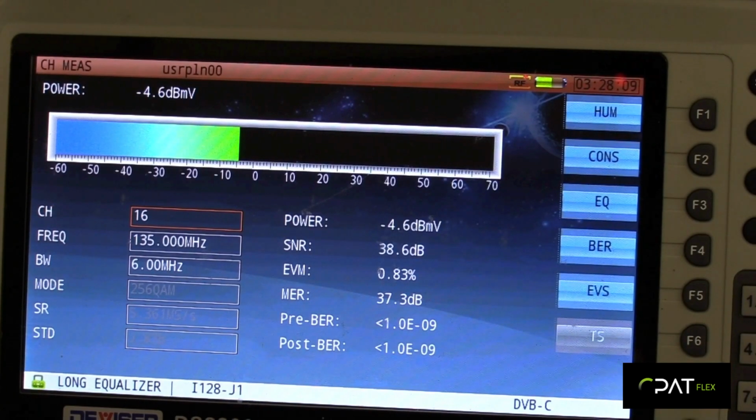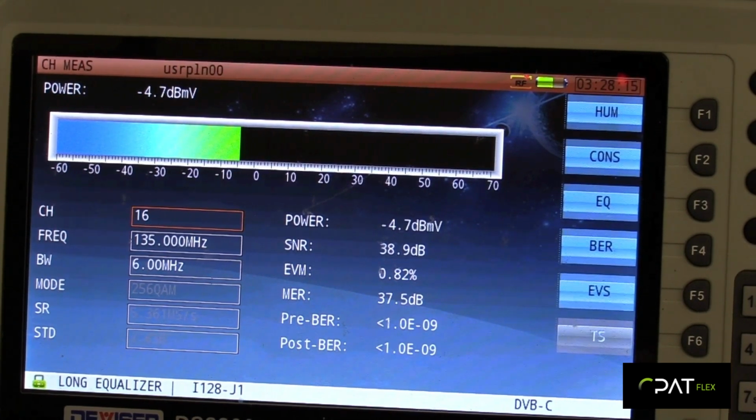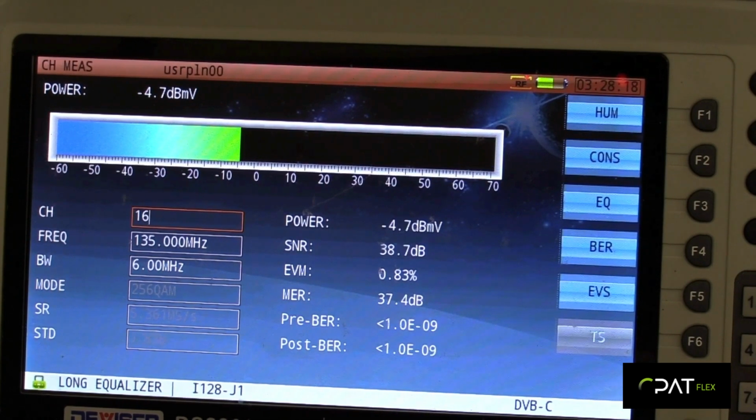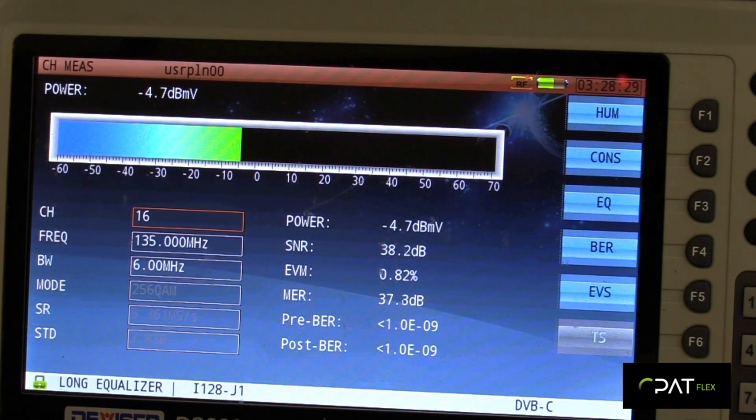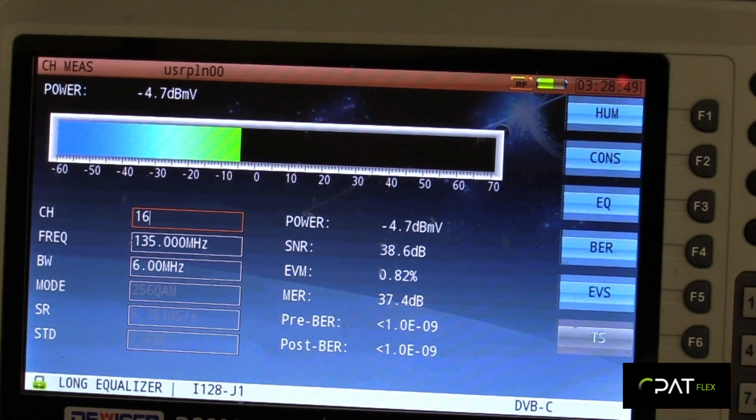Since we need to make digital and analog measurements, ideally you could use a QAM analyzer such as the AT2500RQ or equivalent. If this equipment is not available, you may also use a QAM SLM signal level meter and an analog spectrum analyzer such as the HP8591. For this particular exercise, we are using a divisor QAM analyzer, which will allow us to see both the power of the adjacent QAM channels and the spectrum analyzer screen of the injected carrier.